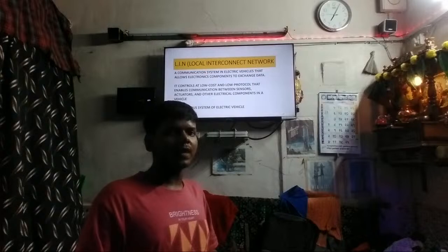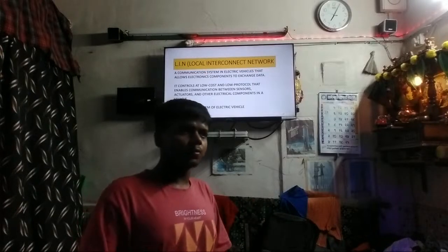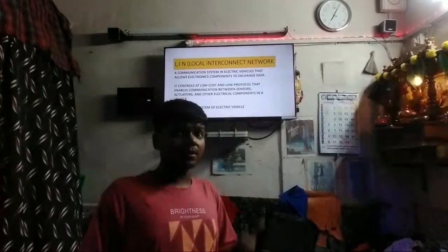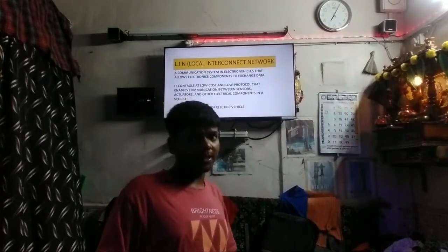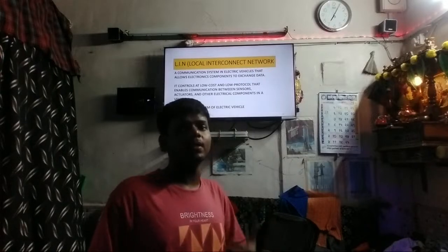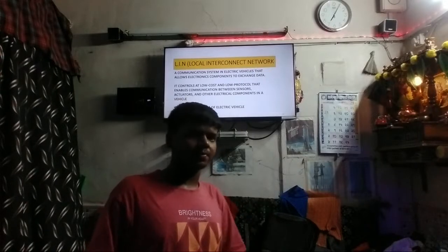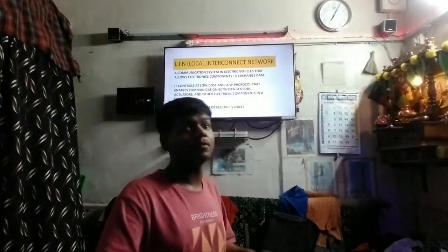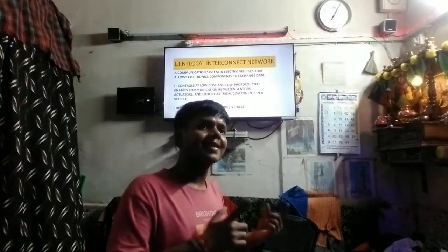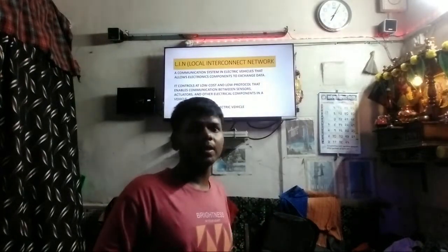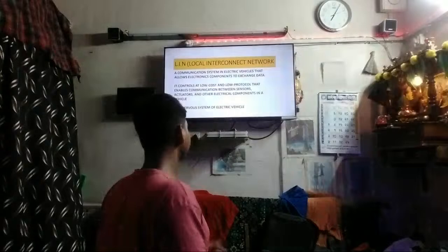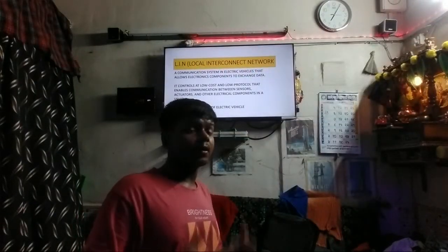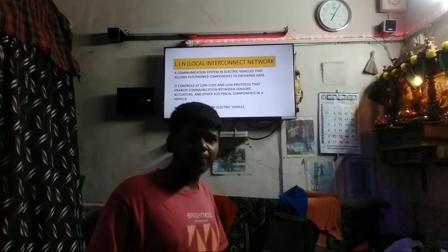So in this flow we have the actuators. Those actuators are controlled by the LIN, because it transmits and receives the data from the actuators and sensors. So this is just the bridge between the actuators, sensors and other electronic components that are used primarily in the vehicle. There's another part that comes with this one, because the secondary system has been controlled. Correct? It has been explained here, right?